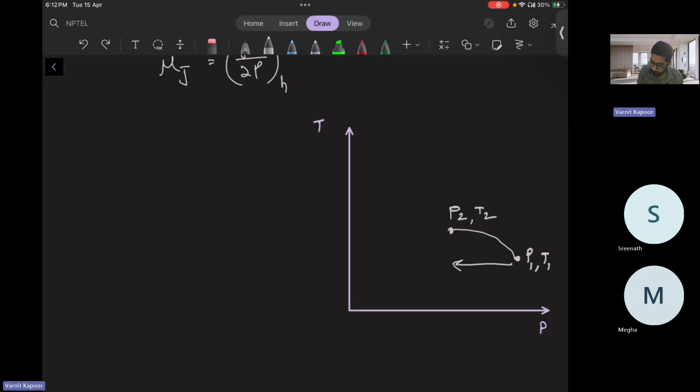All right. Carefully understand this curve. Then, as it's a throttling process, your pressure will significantly try to decrease, but now temperature will also decrease. So pressure decreases and temperature also decreases. So this is P3, T3. Now the question arises: why during throttling is pressure always decreasing from P1 to P3, but initially temperature increased and then it decreased?